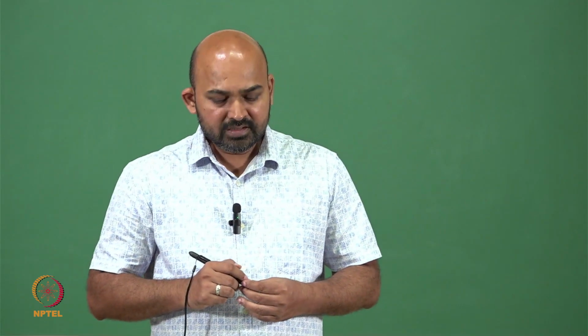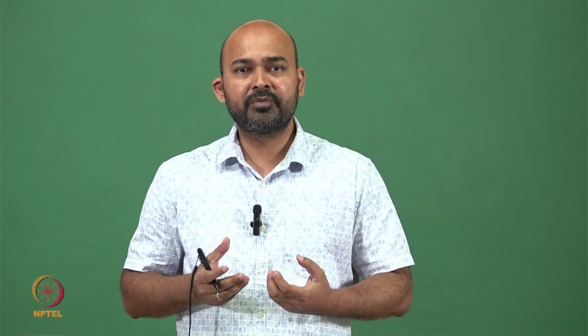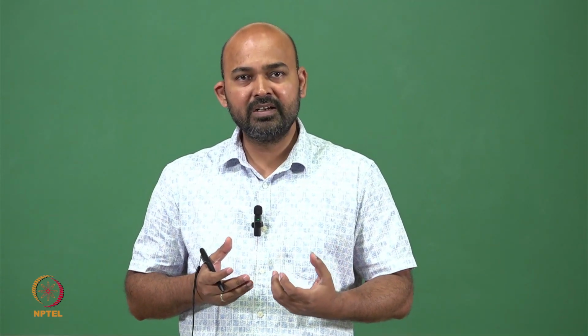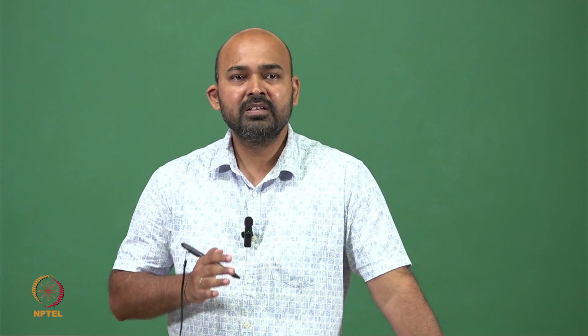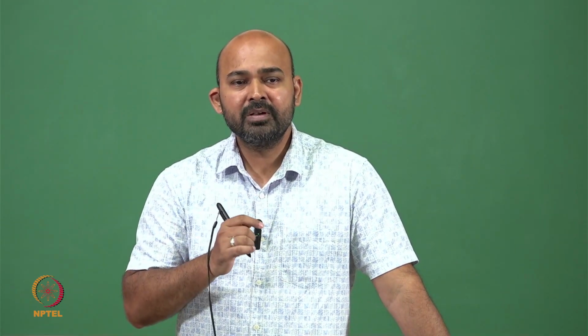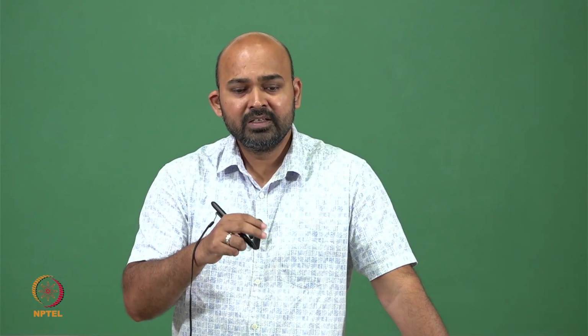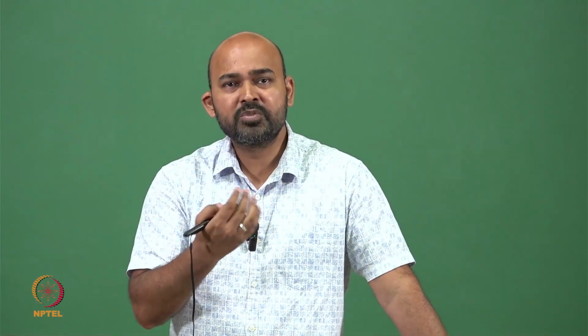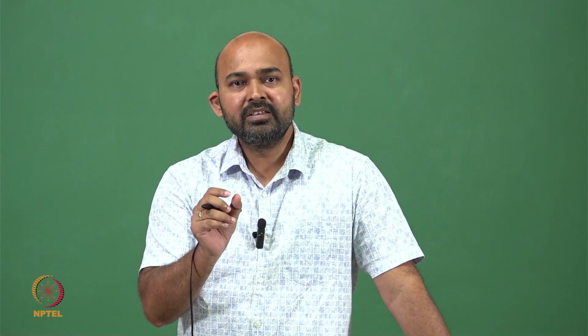So next we discuss the Bragg grating based sensor, which is a different phenomenon of measuring a measurand using the optical properties of a material. In a Bragg grating based sensor, we put a grating in the optical fiber, and depending upon the grating we inscribe on this optical fiber, it absorbs or reflects certain wavelengths of optical light, and depending upon the grating size and grating distance, that wavelength is different.